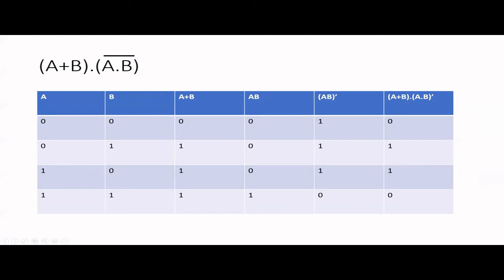So the very brilliant students don't need all these steps, right? You can definitely skip this because in the exam you don't get marks for each of these columns. If you can get the final answer, then that's it, right? And here for that one you get the negation of this. 0 becomes 1, 0 becomes 1, 0 becomes 1, 1 becomes 0. So this is actually our NAND gate, right? And then with this result and this one, you have to do an AND operation. So both the inputs should become 1, then only this is becoming 1.